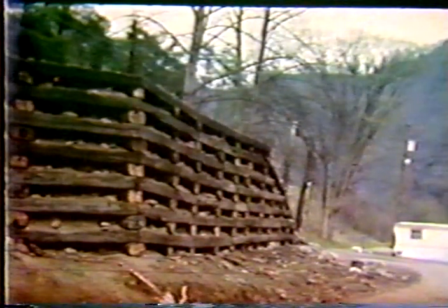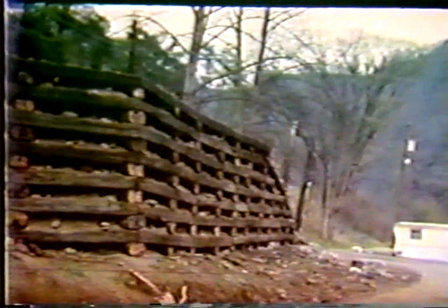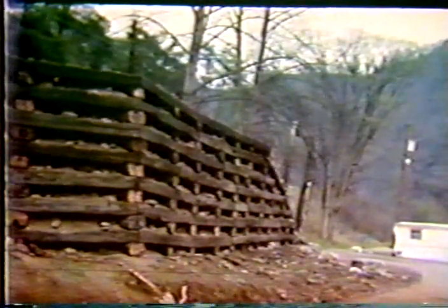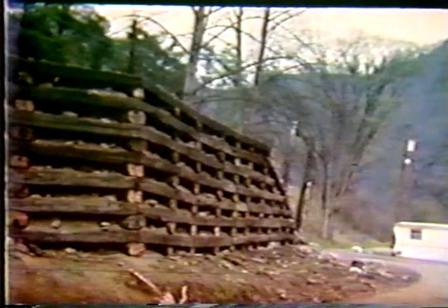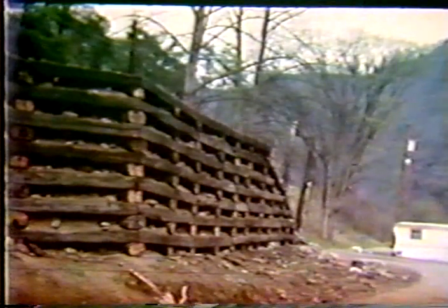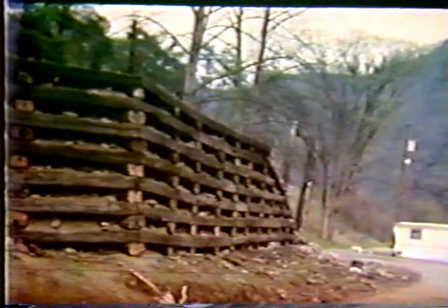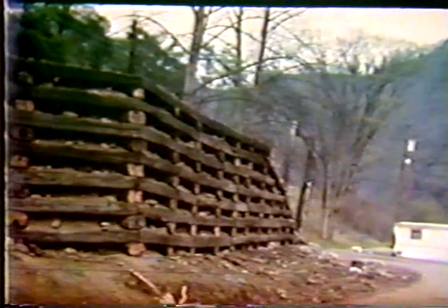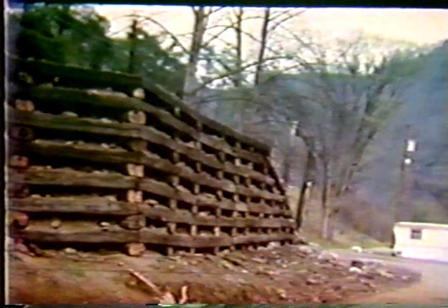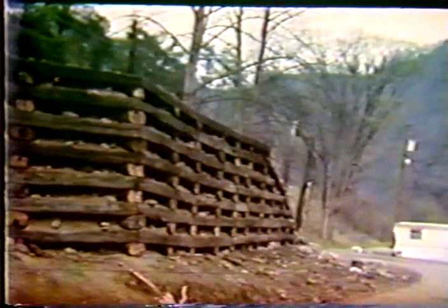In this same county that I was talking about, they had some discarded timber or cross ties from one of the coal companies there, and they made a crib wall. And what they did, you can't see the depth there, but those circular faces there go a few feet back. They're square, probably on the order of 5 or 6 feet square there. And he took those discarded materials, which were given to him. It didn't cost him anything except to haul them out there, and he made him a crib wall to solve the landslide problem there. And he used large spikes to drive those particular materials together.